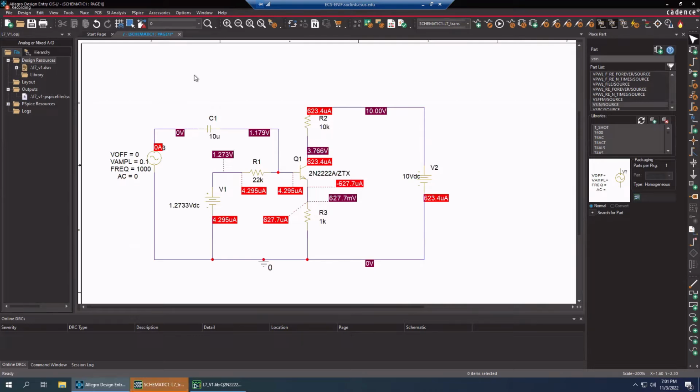Okay, so the voltage at the collector went down, and the current through the collector actually went up. And it looks like we were at like 2 microamps before if I'm not mistaken, or somewhere around that. So it looks like the base current actually went up. So this circuit was affected by the temperature, nothing really dramatic. But anyway, why don't you capture that for step 6? And then when you write your report, you can just summarize all those, like make a little box or table with IC, IB, VC, and just pull them off of the diagram.